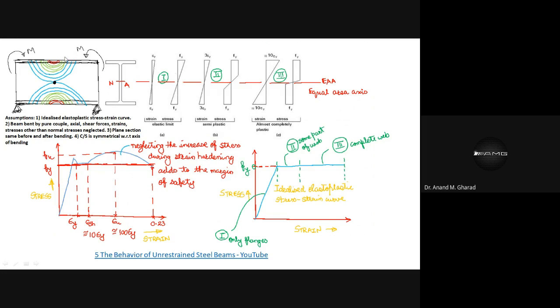If we increase the amount of loading, then what do we observe? These stresses extend from the flange portion up to somewhere over here, the web portion. This is not just true for the compression phase, this is true for the tension phase based on the assumptions we have made. In this case, what will happen? The physical meaning of this figure, that is the second condition, is that the green stresses are developed on the compression as well as the tension side.